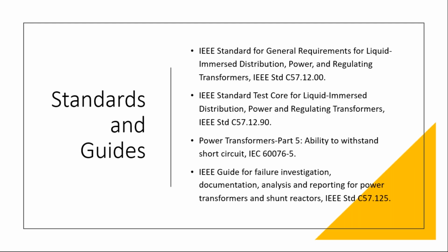And the next one, the design criteria, is covered by an IEC standard, IEC 60076 part 5, which has certain limits on various types of stresses which need to be met during the design phase. Those criteria are based on the experience and practices of other manufacturers.